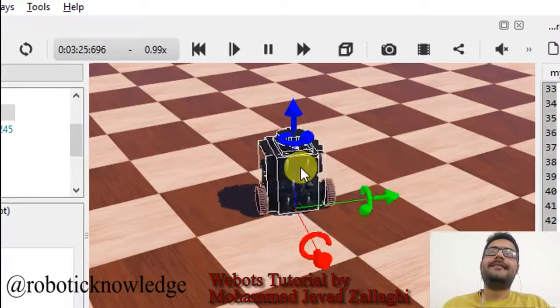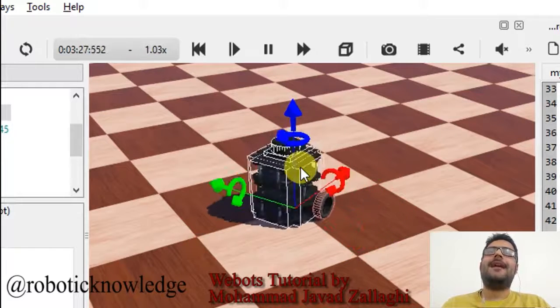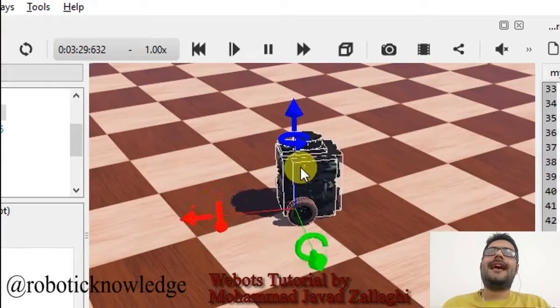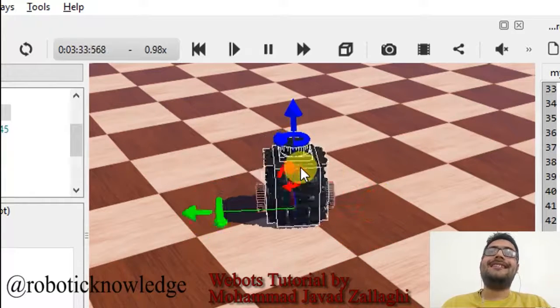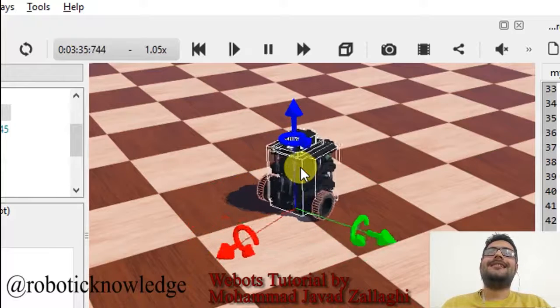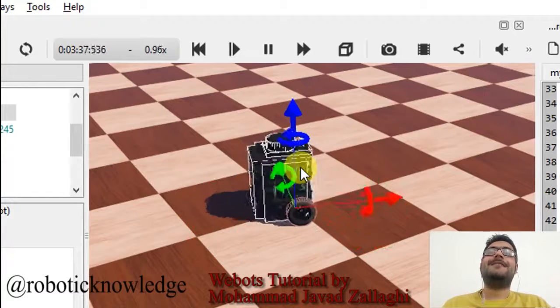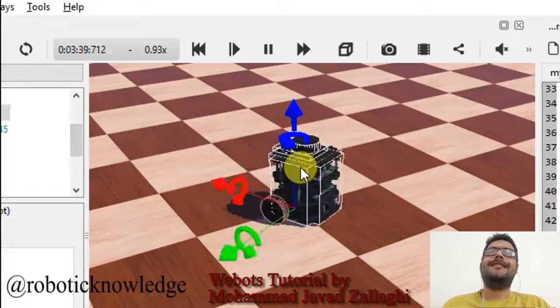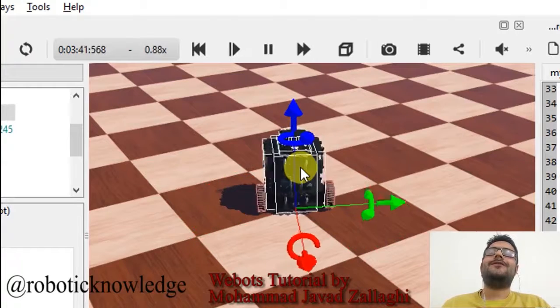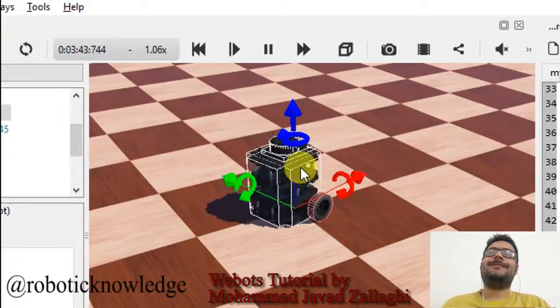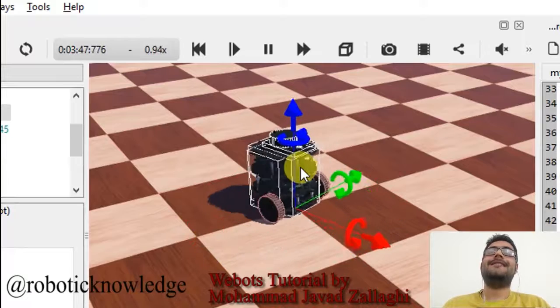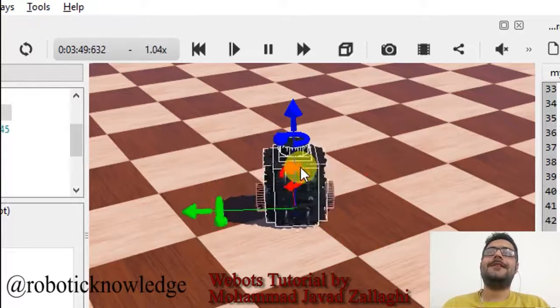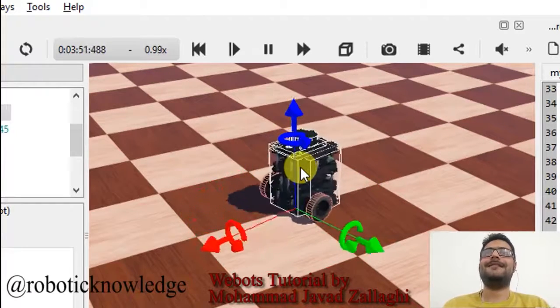Interesting thing here is that the rotation is happening about the z-axis of the local frame, and fortunately the z-axis of the local coordinate is the same as the z-axis of the global coordinate, so we do not need to transform the measurements of the gyro in this specific direction. This makes our work easier.